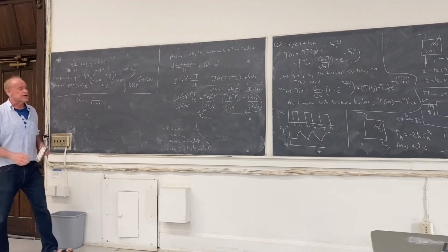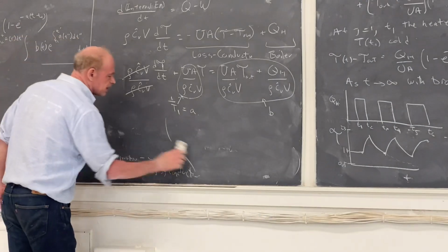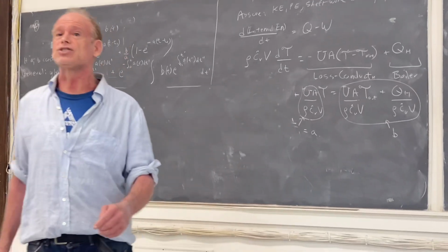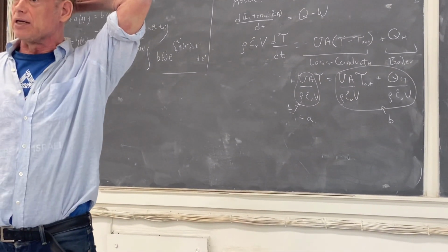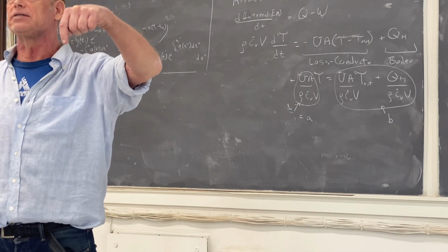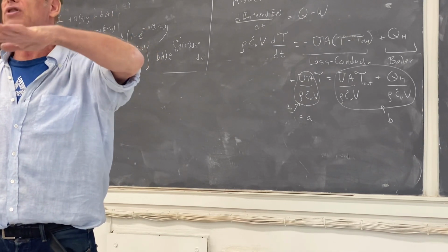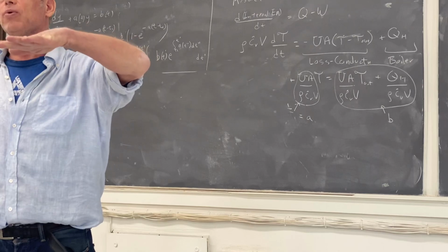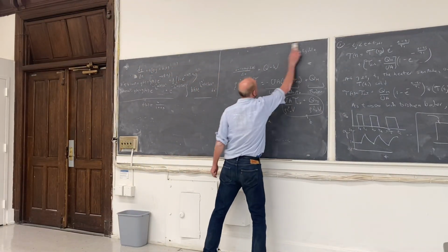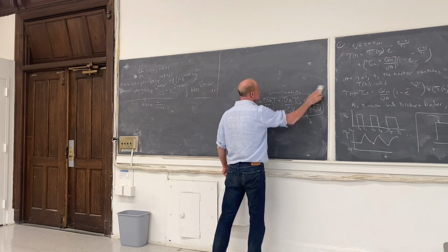And in your kinetics class, you'll see that that is a form that you get often when you have what's called Langmuir-Hinshelwood kinetics, or kinetics where you have something attaching to a surface site on a catalyst, but there are only a finite number of surface sites. So when they're filled up, nothing else can attach. So let's linearize that as well.